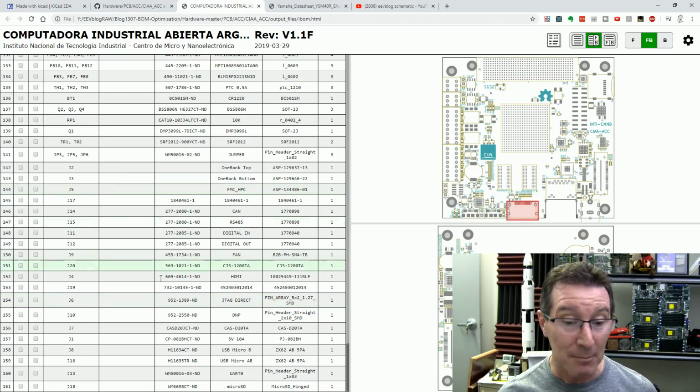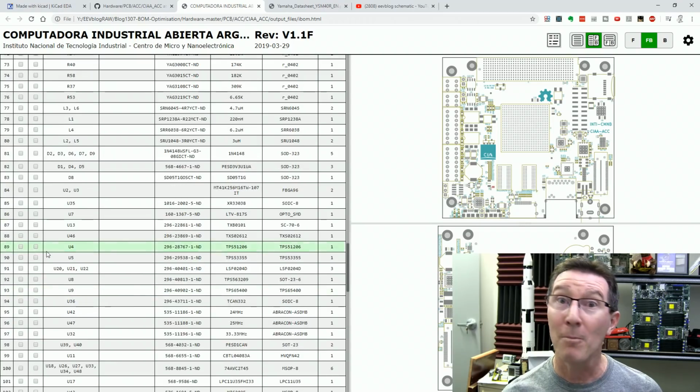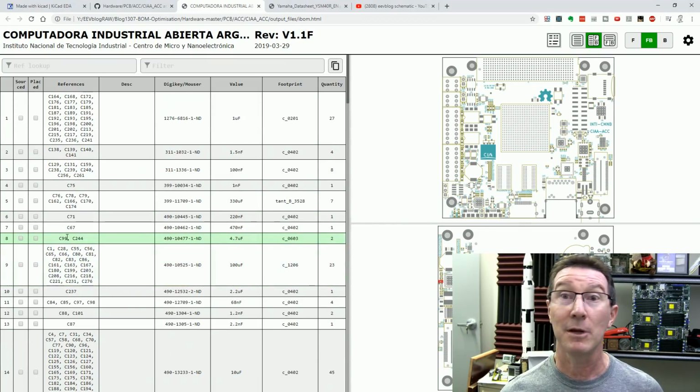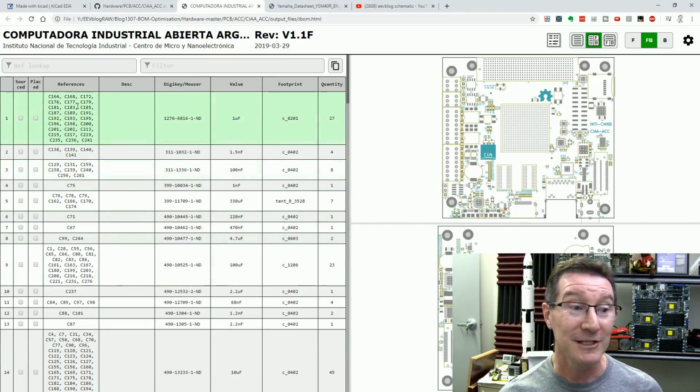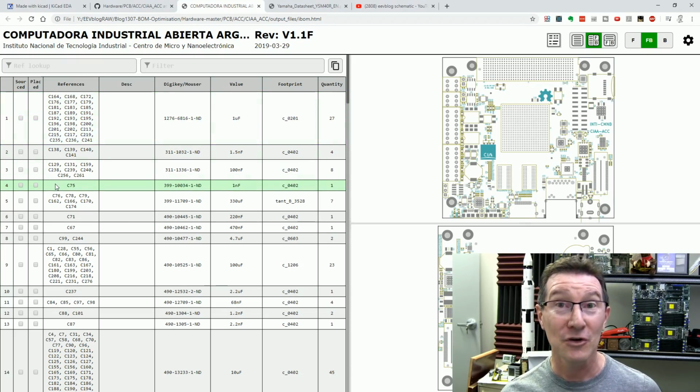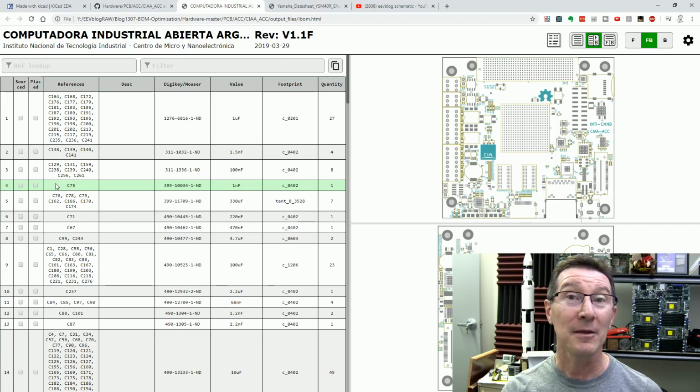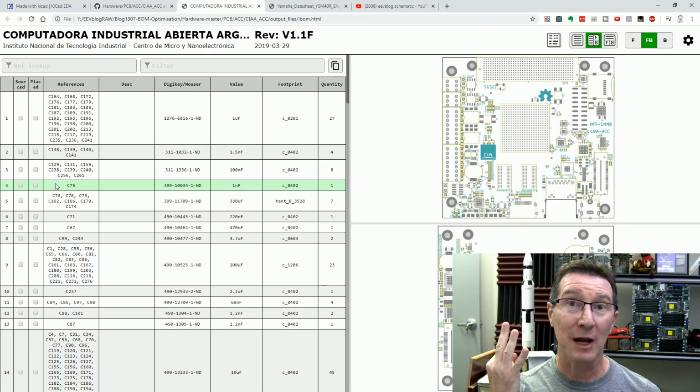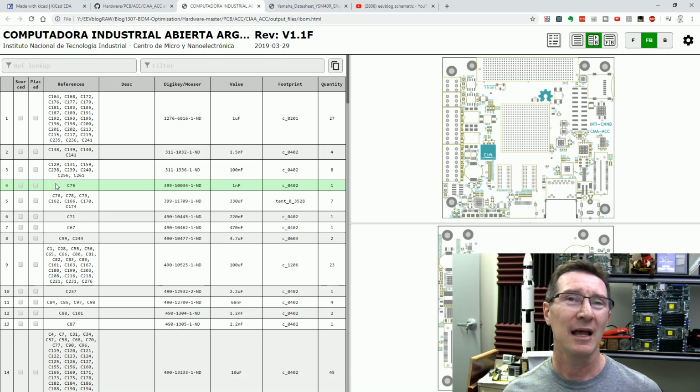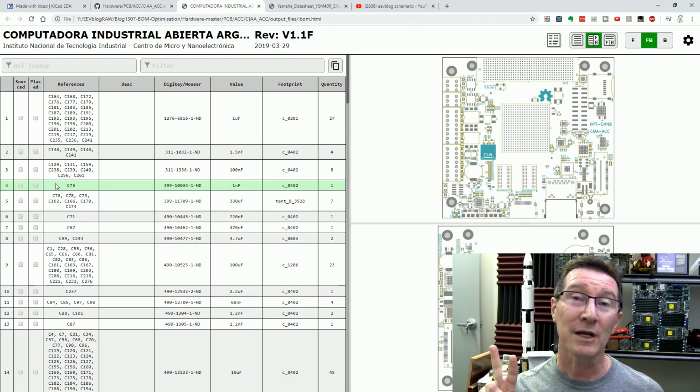You want to minimize the number of different BOM items, bill of materials, by the way, I've mentioned that, haven't I? Bill of materials, the different BOM items that you have, the different parts. There are huge advantages to doing that. And the bigger and more complex your boards get, the more important this becomes. So we talked about 3 different potential ways to do this. The first one is value consolidation, which is generally for resistors and capacitors. There are other components as well, but they're the 2 biggies that you want to consolidate.